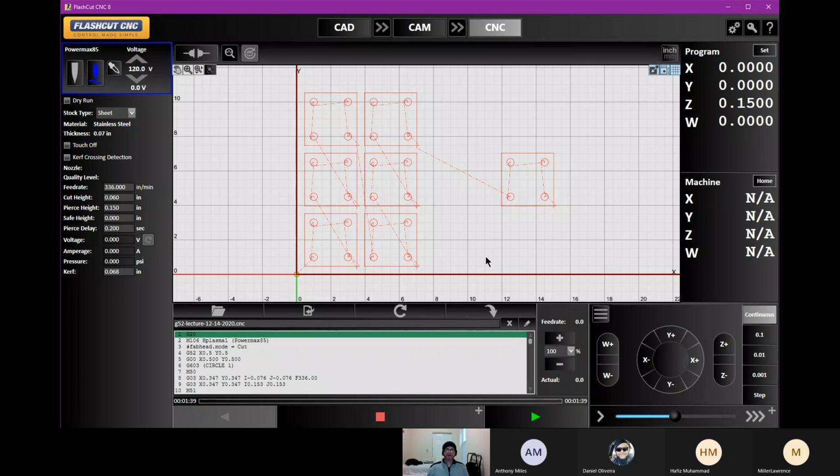Okay. So, like I said, that's the great thing about G52. You can put parts anywhere you want. You can program on the 0 position, which gives us the ability to move it. Sometimes this makes it easy because when you're initially programming a part and we work from the 0 position, we get to use whole numbers or short decimals.